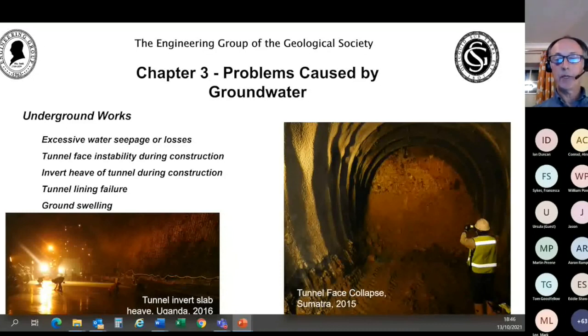The tunnel had been designed to leak, meaning that water ingress would be expected and water pressures would be relieved. However, the contractor, following their normal practice, had installed water bars across the joints in the lining. The result was that the water pressure built up and the temporary invert slab, which hadn't been designed to resist these pressures, blew, causing delay whilst remedial works were implemented.